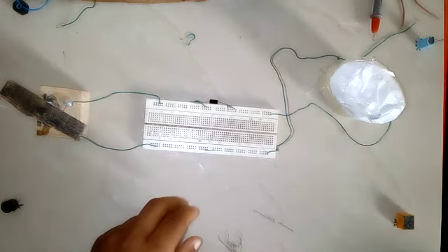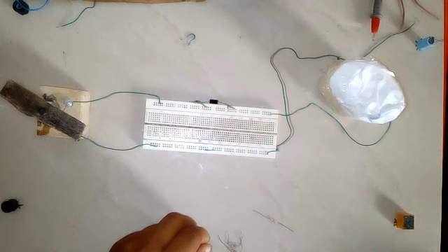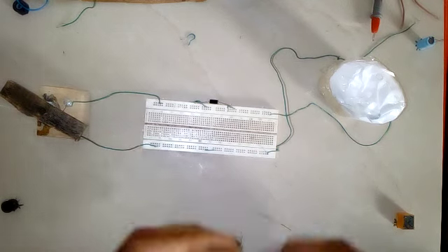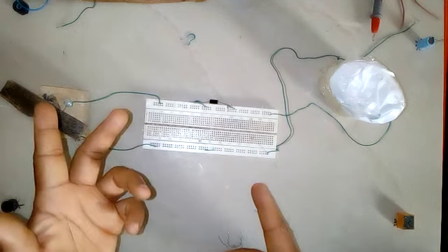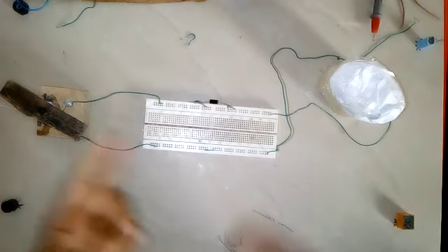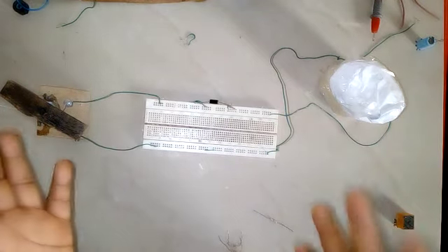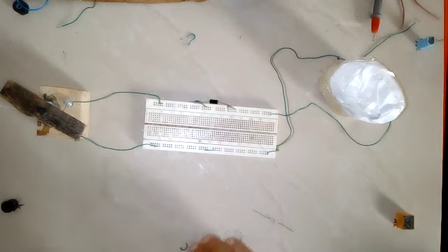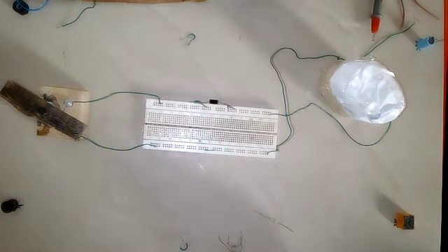So the diode now presents itself as a very large impedance in the circuit because it is reverse biased, because I have not put the terminals on it properly. This is offering some protection to the circuit, especially if you have circuits which are very polarity sensitive and require positive to be attached to its positive terminal, negative to its negative terminal, and not the other way around. If you have a circuit like that and you don't protect it, you will just fry the device, destroy the device in a flash. So keep that in mind.